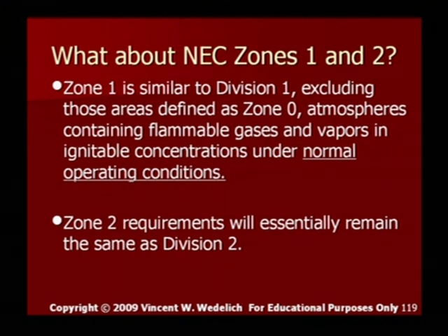What about the NEC Zone 1 and Zone 2? Zone 1, again, is similar to Div 1, excluding those areas defined as Zone 0, atmospheres containing flammable gases and vapors in ignitable concentrations under normal operating conditions. Zone 2 requirements will essentially remain the same as Div 2.